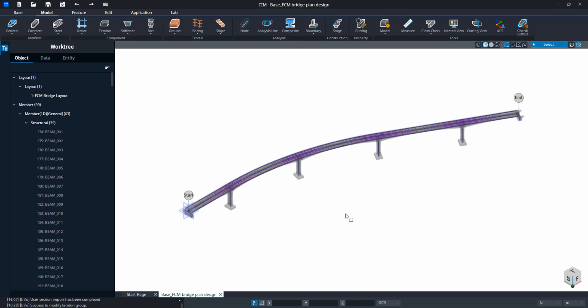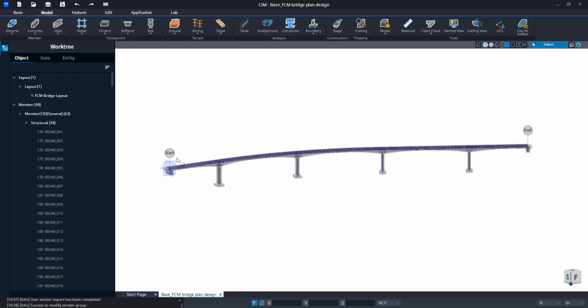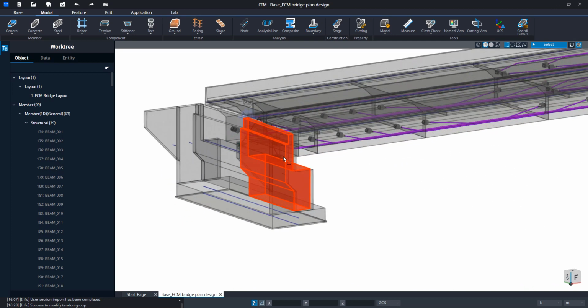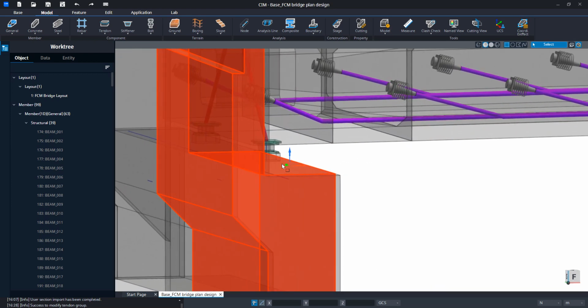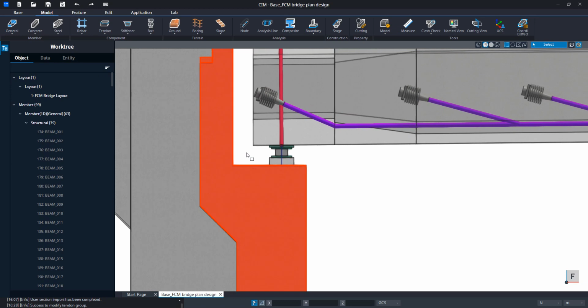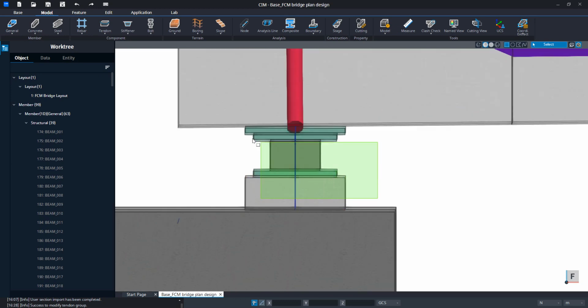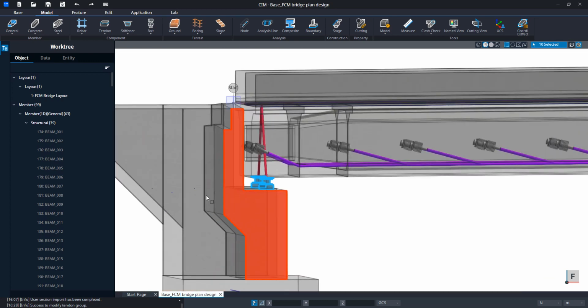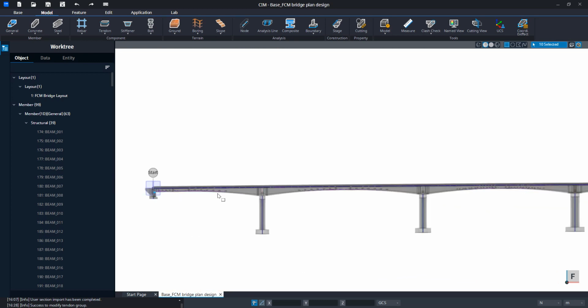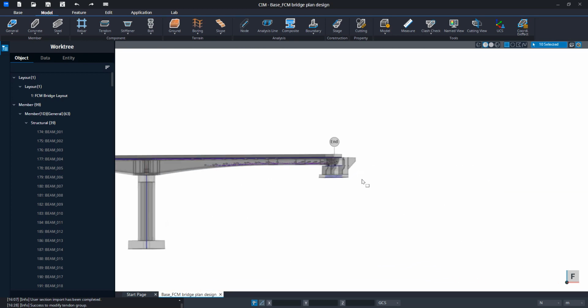And then we are going to create the elastic link. So the elastic link will be in the start part and the end part. And to do that, it's just similar to the last one. We can just isolate this part. You can also isolate the end part.